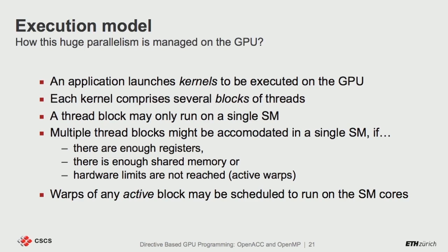So now, it is possible that multiple blocks can run on the same SM. And why is that needed? Because, as I said to you, there are such large resources, like register files, and we want to have lots of warps ready to run in order to cover latencies. We don't have any caches, or any large caches. So the more threads we have, the more likely it is that we can have good performance.